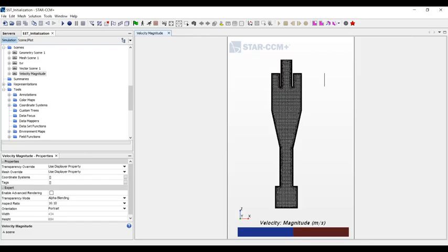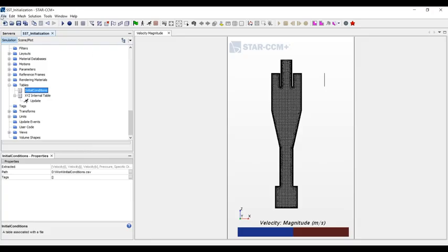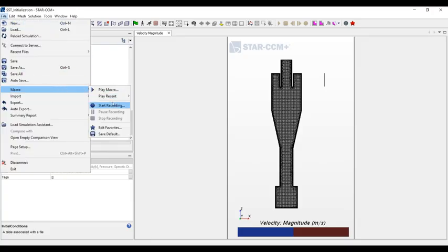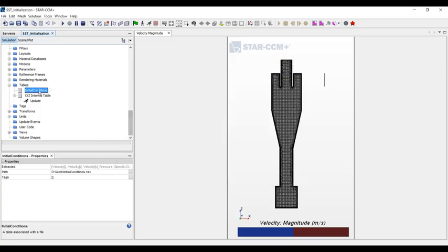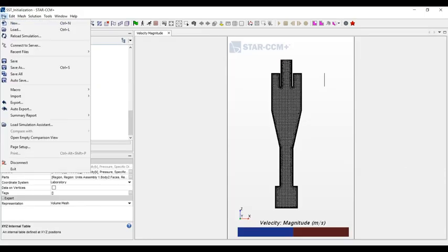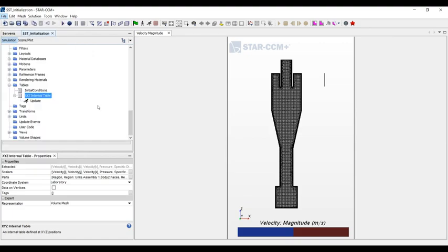When a design is run, there are now two additional actions that must be performed. One is to read the file table to load the latest data available, and two is to save the solution of a simulation to this file table. We will create two Java macros to do this. First, we record a Java macro to read the file table into the simulation. Then, we create a macro to export the results to the file.